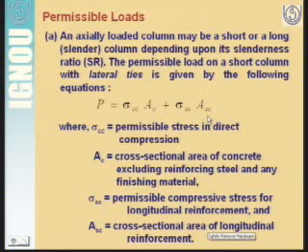So this is your choice, that either you can solve the problem by taking the working stress method or the limit state method. But in the new code, the more stress is on the limit state method. So better to follow the trend which is generally followed by others. So I would suggest you to design the column by the limit state method.